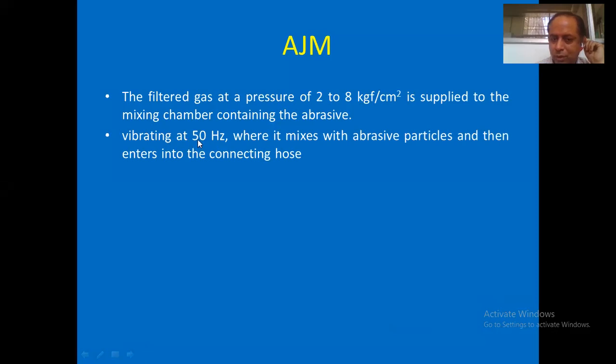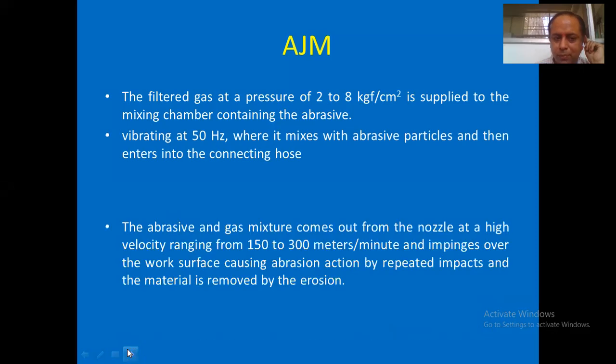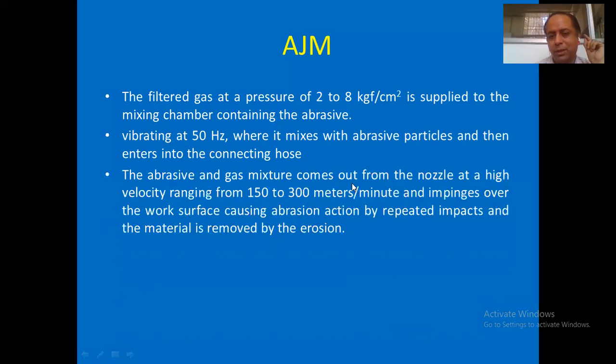So this is again one value: the vibration we mentioned happens at a certain frequency, 50 hertz. The abrasive gas mixture comes out from the nozzle at a velocity. We already discussed this point. This velocity should be in seconds, not minutes: 150 to 300 meters per second.